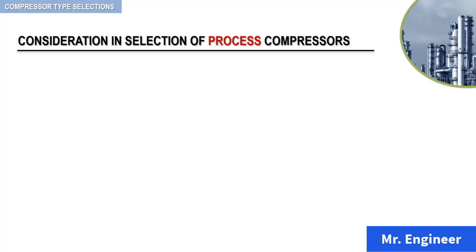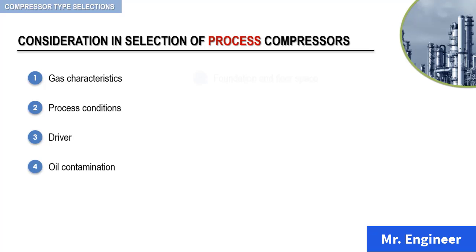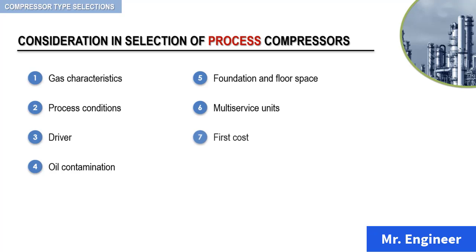These considerations include many factors. First, we list them, then we will see each one of them in detail. Among these considerations, we have gas characteristics, process conditions, driver, oil contamination, foundation, multi-service units, first cost, and power cost, just to name a few.